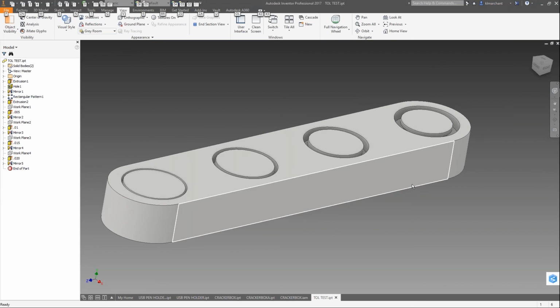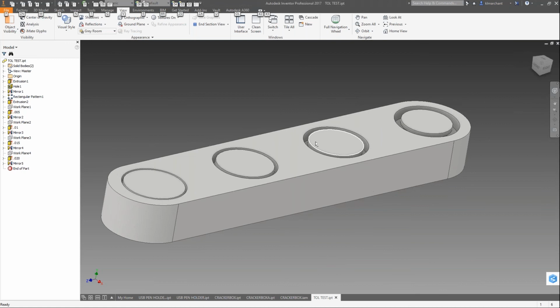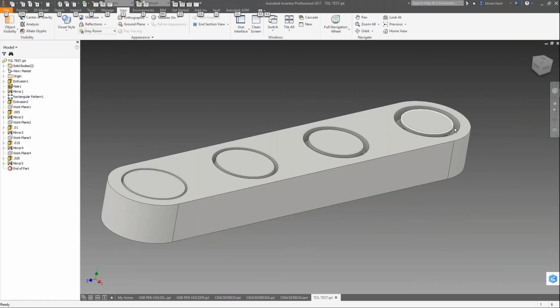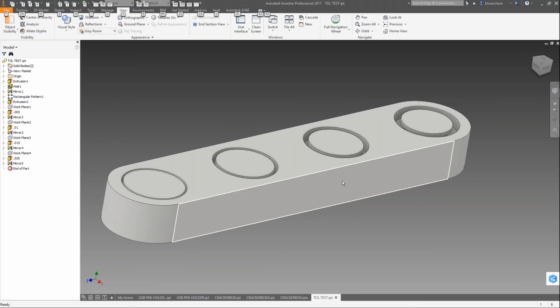So then I know when I create text or a label or anything like that with my print, I know how thick those need to be: A, to be visible, and B, to be able to clean that wax or support material out of, so that feature is visible. That translates over into any kind of recesses. If we need to make a pocket to apply a label on our print to look like the real product, all those kinds of tolerances really help figure that out.